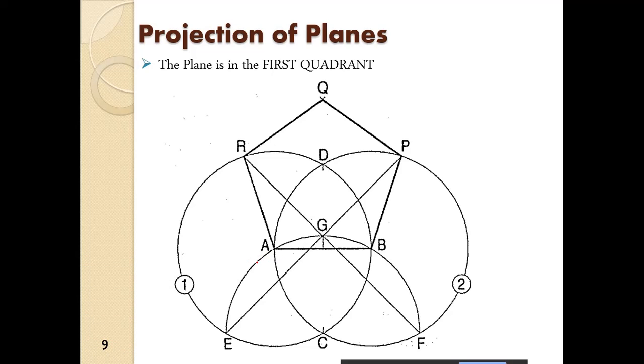So first step is the AB side, the length of the side AB will be given, so you draw AB. First step. Then with AB as radius and A as center, you draw this circle. This circle. Okay, and then with B as center, you draw this circle.